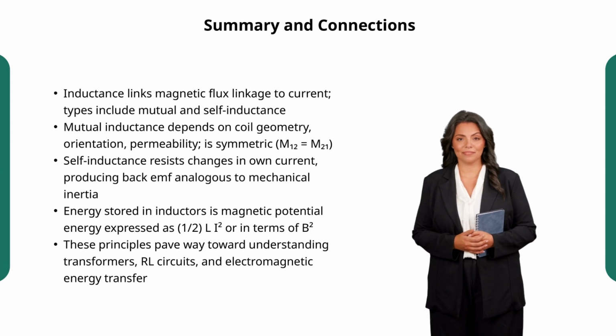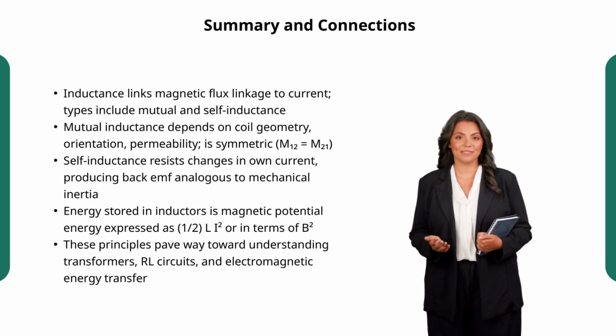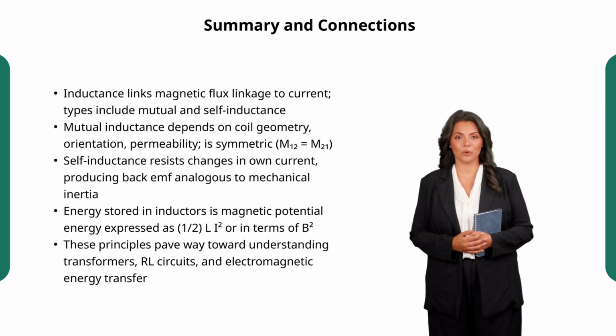To wrap up, today we have developed a comprehensive understanding of inductance. We began by framing inductance as the proportionality between magnetic flux linkage and current, introducing mutual inductance between coils, which depends on coil geometries, their relative positioning, and the medium's magnetic permeability. We proved the powerful reciprocity that mutual inductance is symmetric. The flux induced by one coil due to the other's current is equal in reverse configuration.